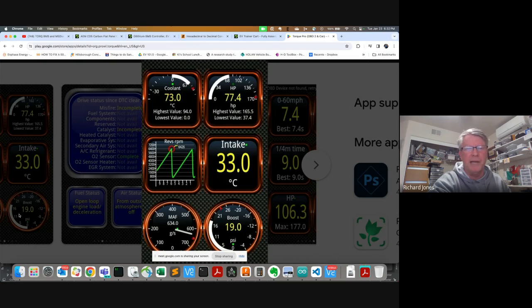And I've spent many, many hours coding up the gateway software that basically understands CAN bus on one side and then invents special messages for Torque on the other that shows all these cell 1 through 128, same for temperatures, motor controller. I had to create what they call custom IDs because they're not standard in the smog testing of a car, which is what OBD2 was designed for. Right, smog testing gas cars. So everything has to be sort of custom on there.